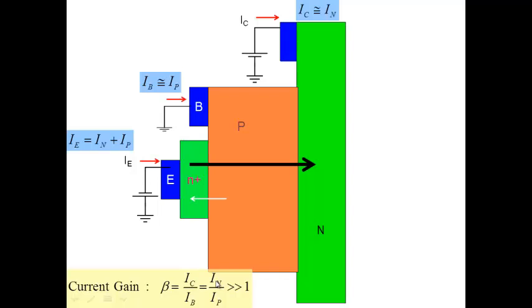Now, one way of looking at a bipolar transistor is the following: you change the emitter voltage, and as you change the emitter voltage, what happens? For example, if you increase the emitter voltage, this current will increase, this current will increase, and therefore this current eventually flows here, and thereby you increase the collector current. So as you change the emitter base voltage, what happens to the collector current? It increases. And what will be the relationship between them? If you increase the emitter base voltage, how will this current increase? Exponentially, right? Each one of these currents is exponential with voltage. So this current increases exponentially, and therefore this current increases exponentially.